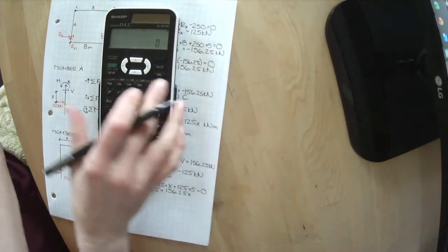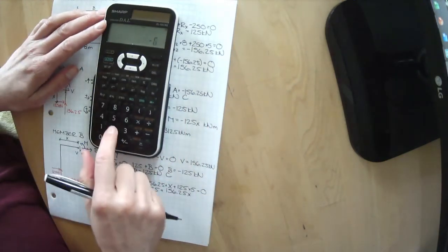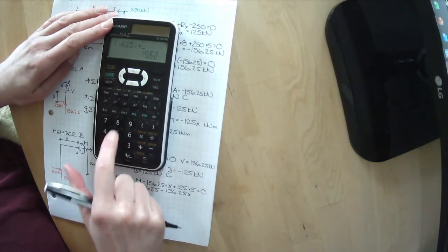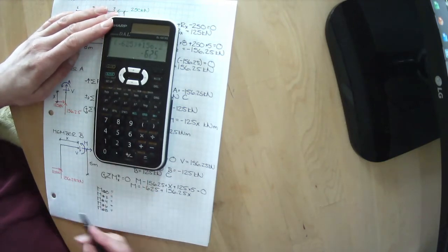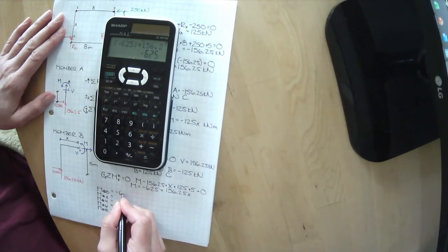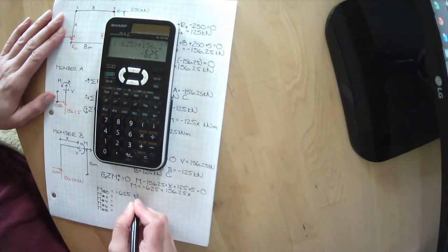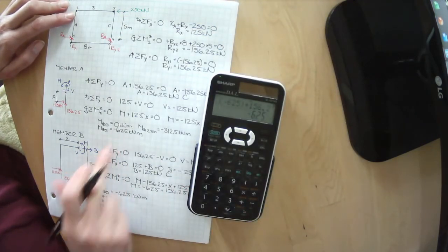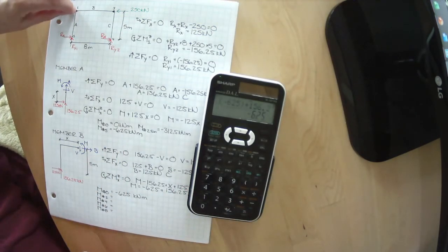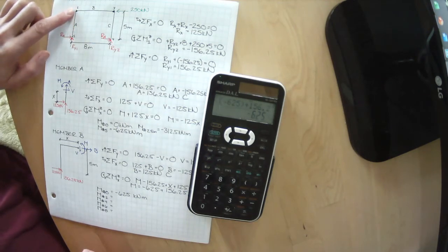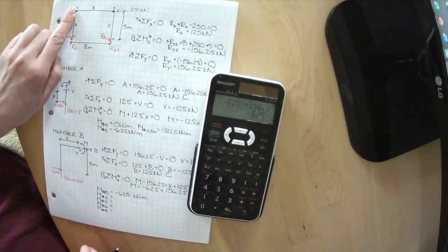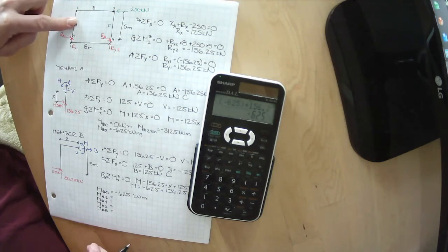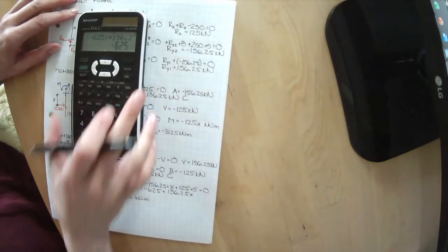All right, at 0, we have minus 625 plus 156.25 times 0. Well, our moment is minus 625 kilonewton meters. Ooh, A had 625 kilonewton meters. So it looks like that 625 kilonewton meters that's in A can transfer to B. There's continuity there in the moment between those two members.